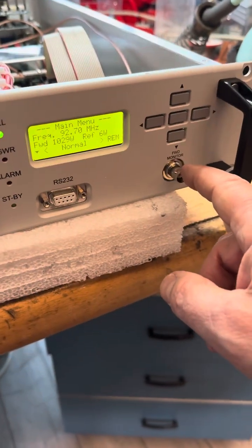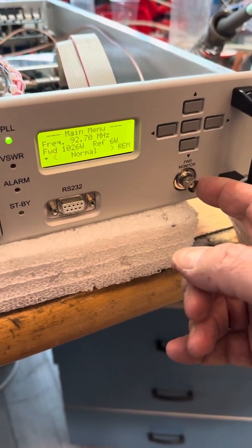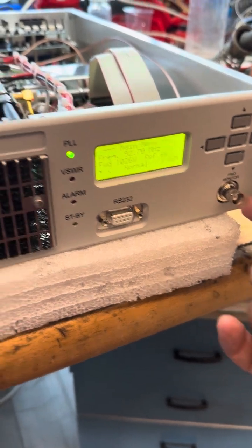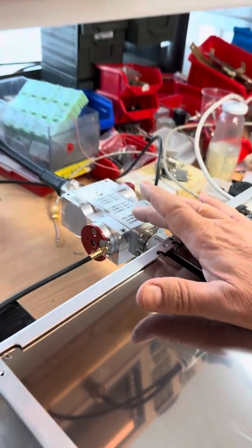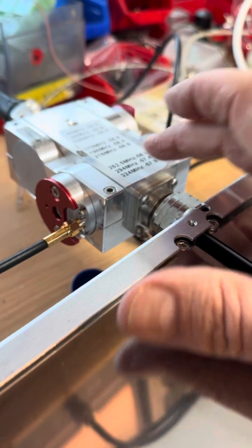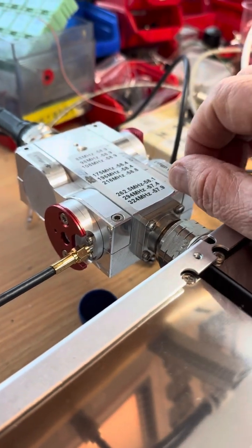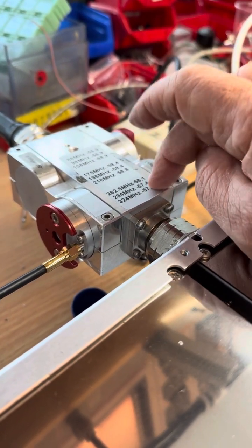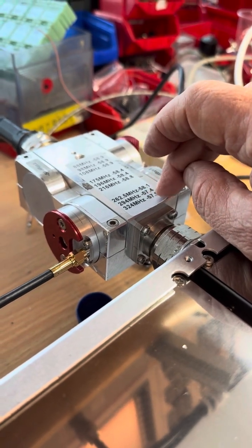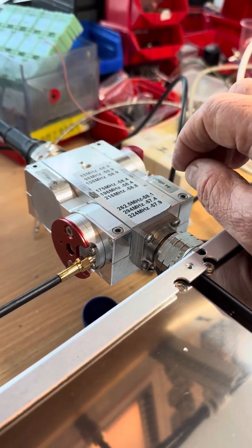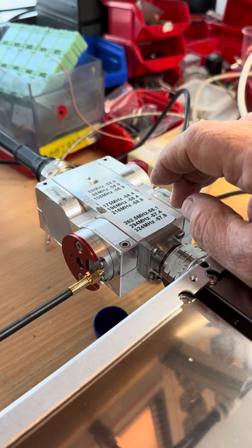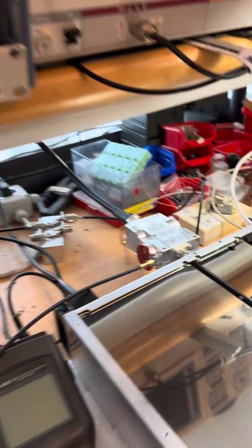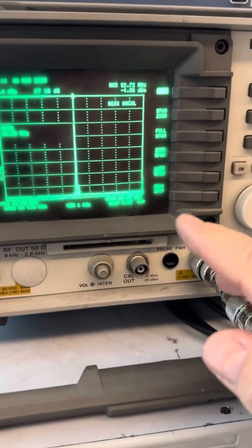You can never use, for example, this output to measure harmonics, because this is not calibrated in frequency. This is an RF sample. Okay. So this is a kind of measurement that must be done with a coupler, then we know exactly how the band is, and that it must be linear. Often this kind of coupler has a very high amplification at high frequencies, so we must pay really good attention to this. This must be very well measured with a network analyzer. In any case, I will show you now.